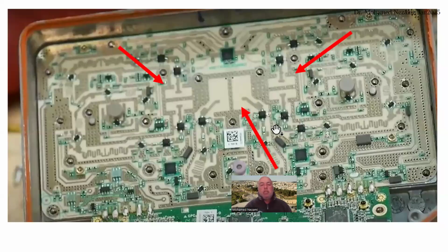Just to show you more interesting LNBs, here's one that has, let's see, 1, 2, 3 waveguide signals coming in. That's 6 programmings on this one, 2, 4, 6. And you can see the waveguides in here, the interface, the rectangular waveguide. This one here is really a square waveguide, unlike this one here, which is a circular waveguide. That's why I kept both square and circular waveguide to illustrate.